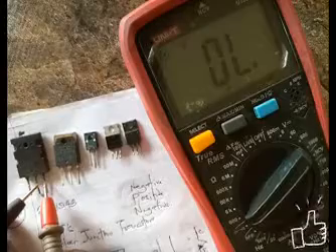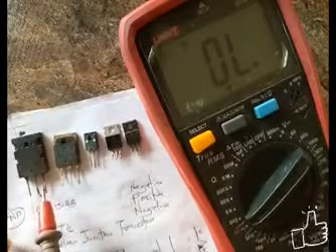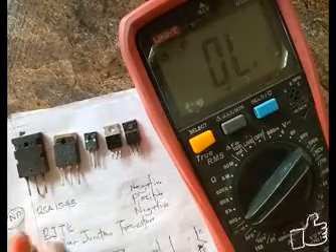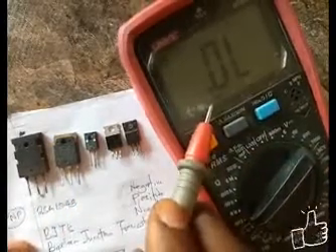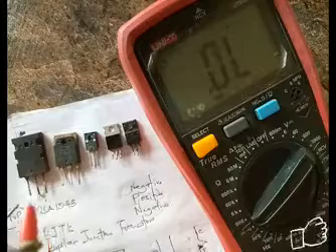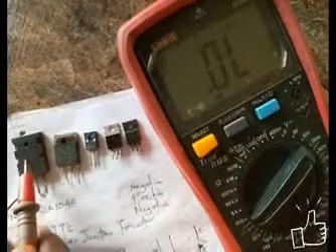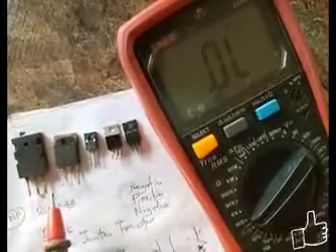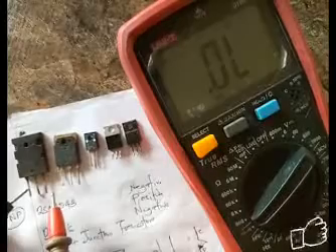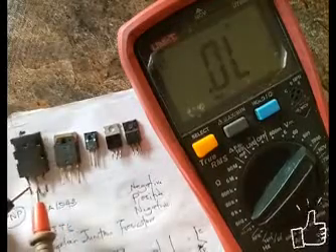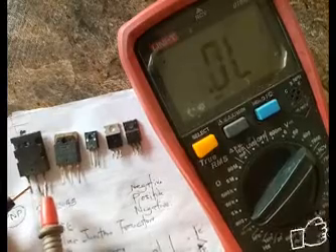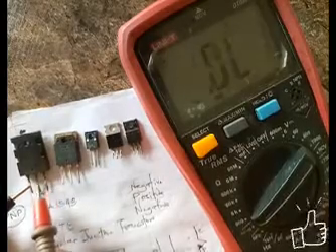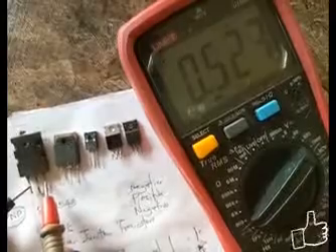So it's not shorted. It means that it's not joined, which tells us in the first place that we can continue with our tests. Now, the next thing is to switch it to diode measurement. And then, knowing that this is PNP, it means our negative probe would be on the base. Okay? Now, we'll get a reading, base collector, base emitter, base collector, base emitter.